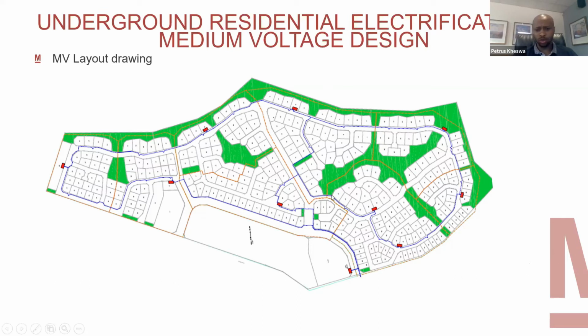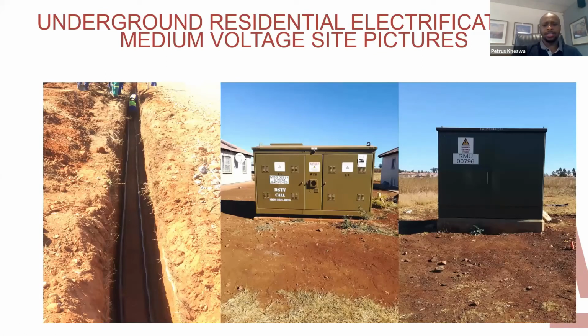And so that's essentially how we go about designing the MV network. This is just an indication of pictures that we took in one of the projects. As you can see, the guys here were busy installing the MV cable. In the picture you can see the depth of the trench, which is 1 meter deep. As I've indicated on the derating factors, the cabling needs to be properly spaced so that you also try not to derate the cables.